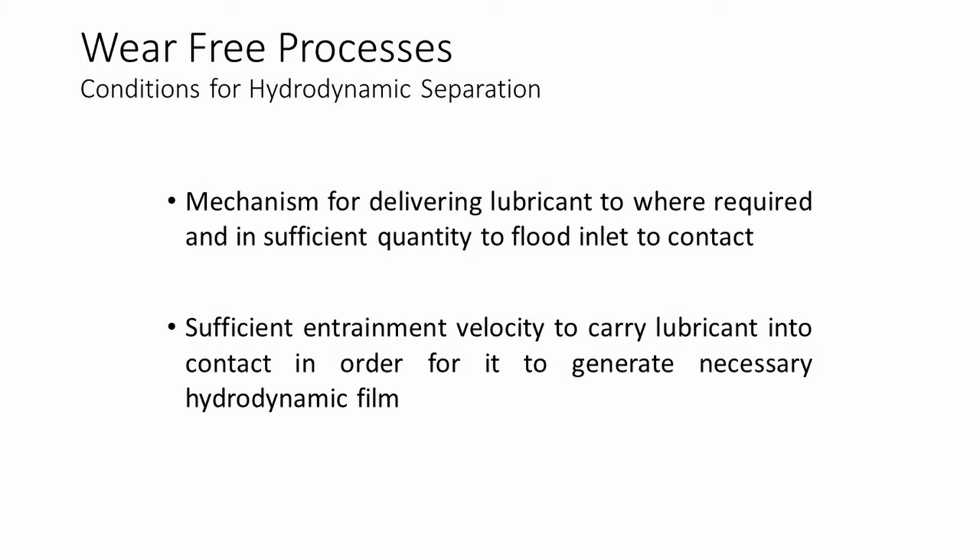The problem is that in order to generate hydrodynamic separation of the surfaces, any system must fulfill two requirements. Firstly, there must be a mechanism for delivering the lubricant to where it is required and in sufficient quantity to flood the inlet to the contact.